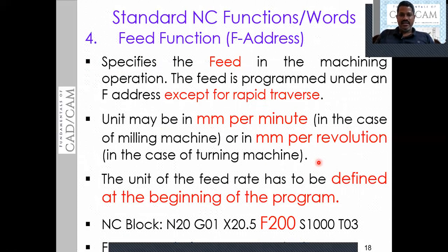Then let me move further to discuss what the feed function is. For each operation, the feed may be different. The feed of a finish cut is different from the feed of a rough cut, so in each block of statement we need to specify the feed if we want to change it as per our requirement. This unit also varies from machine to machine.